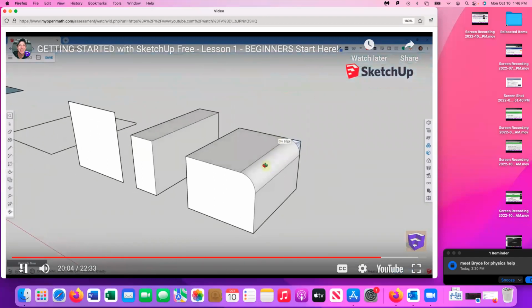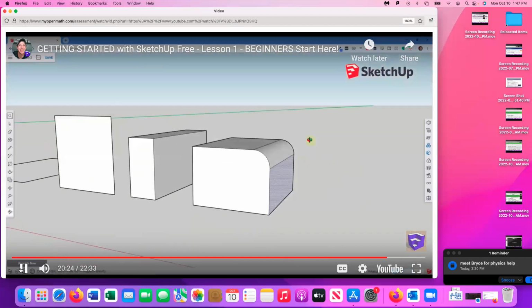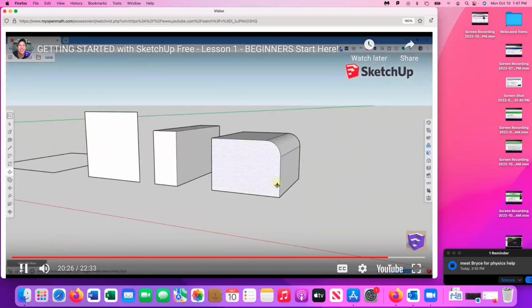One thing you're going to notice is if you move your mouse all the way to the back and then click anywhere along this edge right here, SketchUp is going to automatically delete the material that was left over, because it's using its inferencing engine to figure out that you've removed the material all the way along an object, and it needs to delete this flat plane right here. This works for curved edges. This also works if you were just to draw a single edge across here. You can push pull that and then click on this back face.